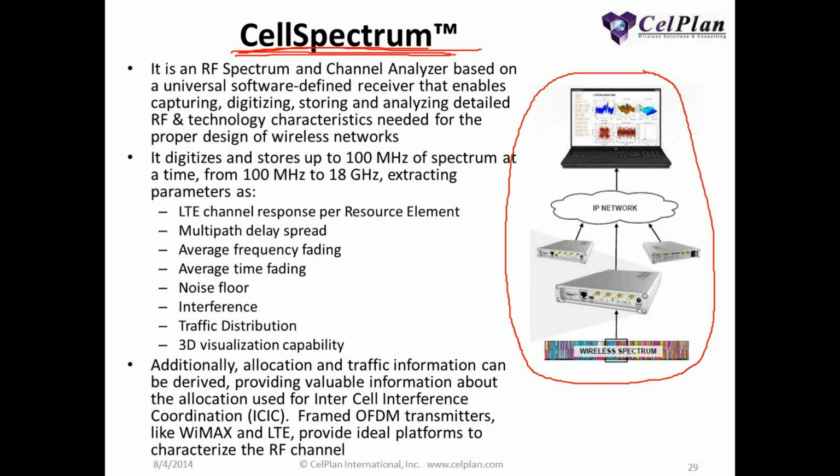It's an RF spectrum and channel analyzer. It's a totally software-defined receiver. By being a software-defined receiver, it is really independent of the technology, and it enables capturing, digitizing, storing, and analyzing the RF spectrum, and then we can analyze any technology. At this moment, we are doing LTE FDD, but our plans are to extend this to other technologies. The good thing is that it digitizes and stores up to 100 megahertz of spectrum at one time. So you can have a lot of information there.